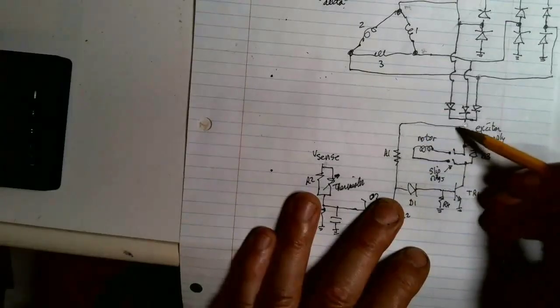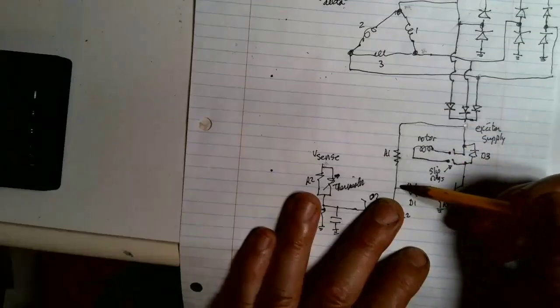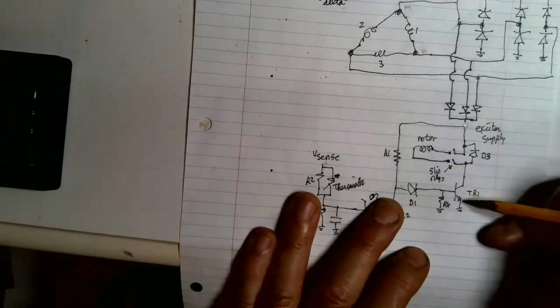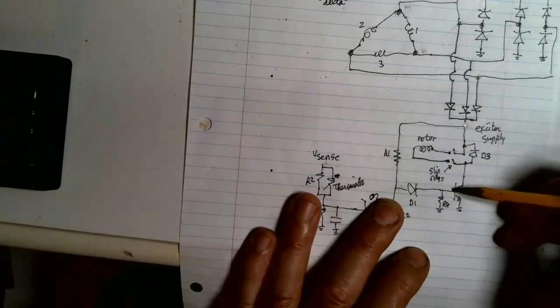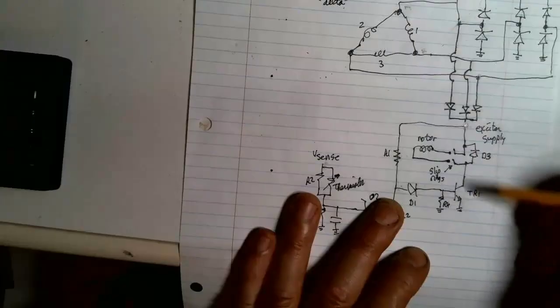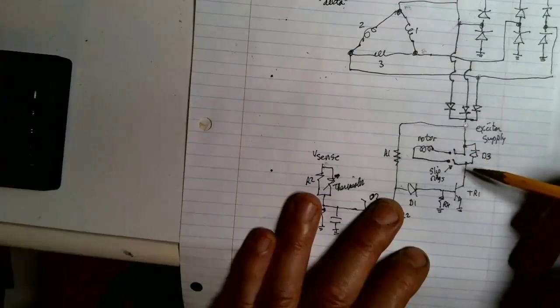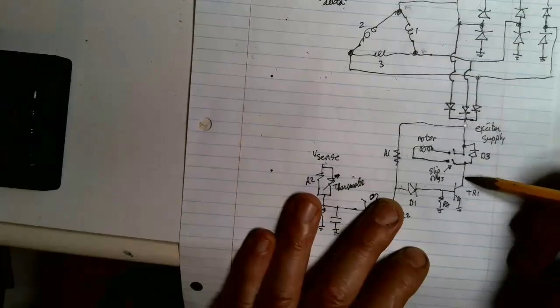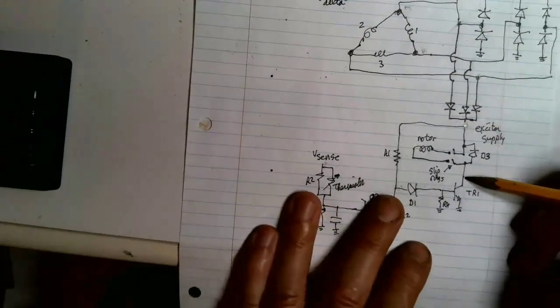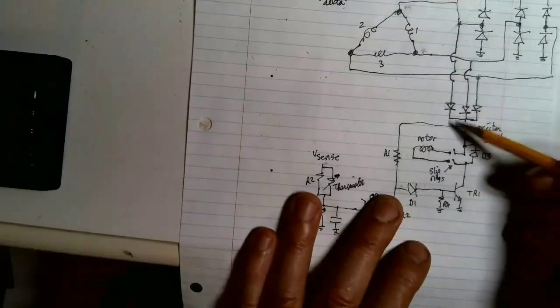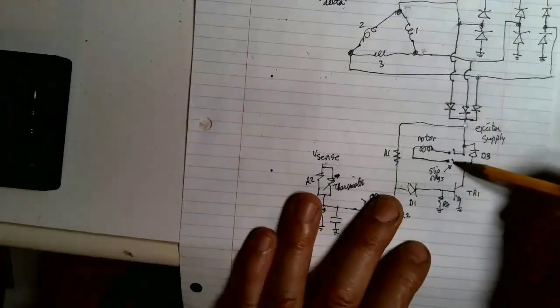So the drop across this resistor is 14.5 on this side, 1.4 here. 14.5 minus 1.4 divided by R1 is the base current to TR1. Hopefully, that base current times the beta of this device, at least 100, let's say, would be more than enough to handle the 3.5 amp rotor current, to allow this transistor to come pretty close to saturating, because that's what has to happen when the alternator runs wide open. This resistor biases up TR1, turns it on, and allows current to flow through the rotor to ground through TR1.